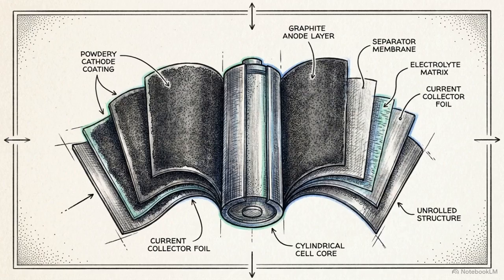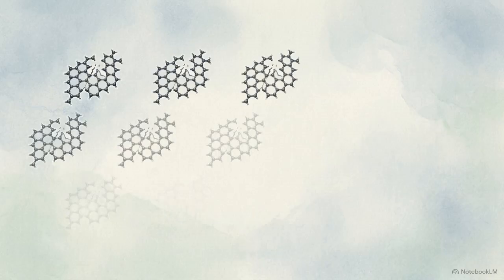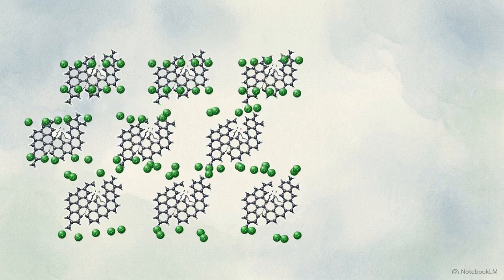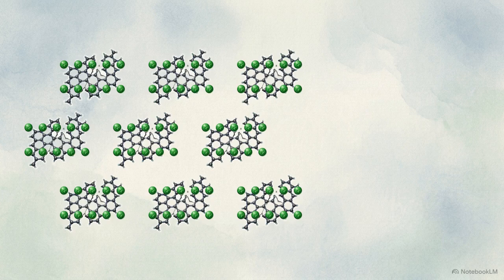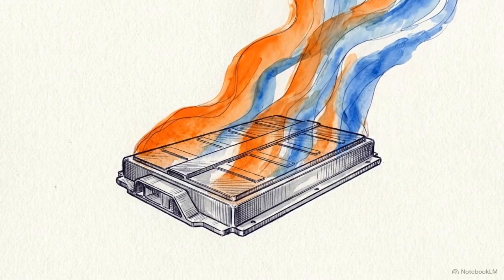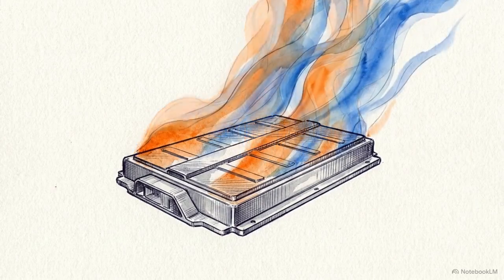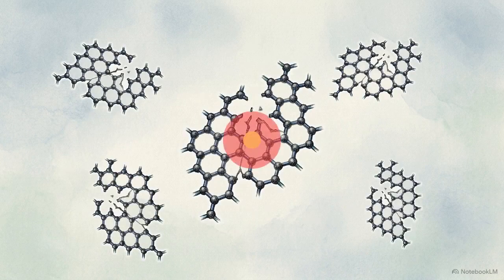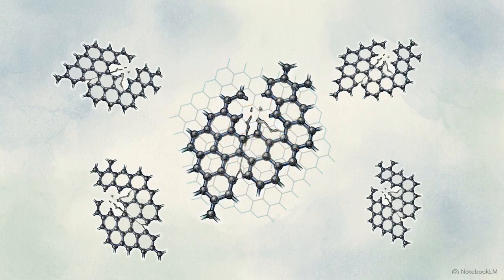Energy storage engineering, particularly the development of lithium-ion batteries and supercapacitors, utilizes a different physical variable entirely. Liquid phase exfoliated flakes maximize the exposed geometry of the 2D plane, providing a massive surface area to volume ratio. This physical density accommodates significantly more ions, decreasing charging times while increasing energy capacity. In thermal management, engineers incorporate graphene into heat sinks and thermal interface materials, particularly inside high-density electric vehicle battery packs. Even in fragmented forms, the 120-degree atomic geometry efficiently channels heat away from localized hotspots, preventing catastrophic thermal runaway.